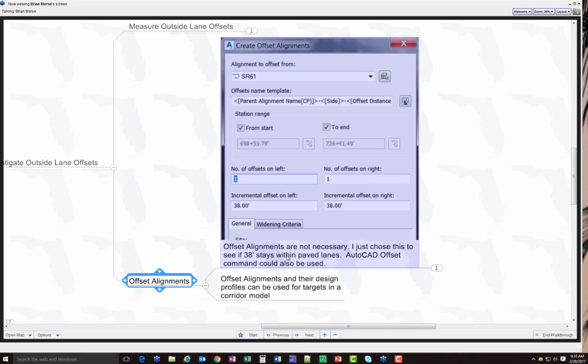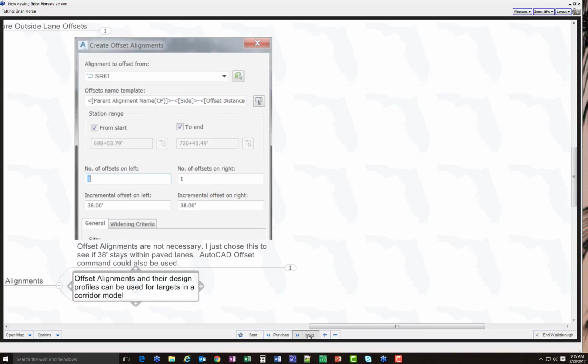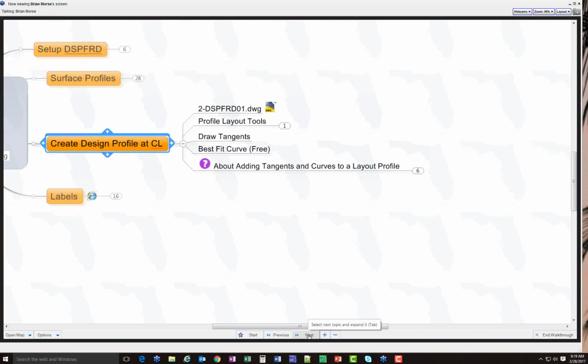And that way you're not using the super elevation calculations, you're just mimicking that with profiles of objects that are already out there. So, if you're doing milling and resurfacing, maybe it's not going to be ideal, perfect geometry that you would match the standards, and you just want to match the existing conditions out there. So that was just a little aside on that.